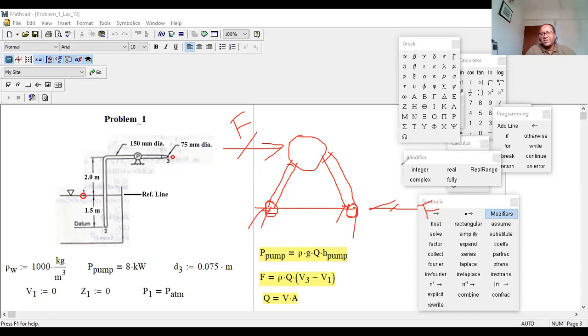The upper one is pulling right, the bottom one is pulling left. It is like somebody pulling your head toward the right and your leg toward the left. What will happen? Your body will rotate. So how are you going to protect against this rotation? Which way? Anti-clockwise, right? So due to this anti-clockwise rotation, you see what will happen. If your support is, say, on clay, then what will happen? This will go down and this support will go up, right? So you need to protect that. That means due to the rotation, this support will try to go downward and this support will try to go upward, but you have to protect against that motion.